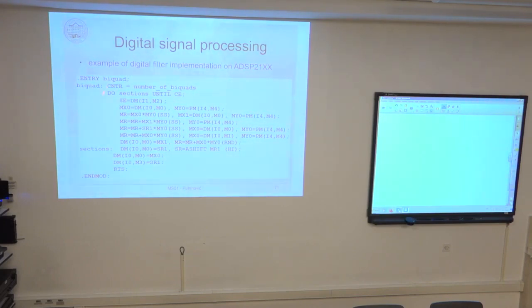And you have a dual loop, and this dual loop is also a hardware controlled loop. It has dedicated hardware support to implement a zero overhead loop. Normally, for a classical architecture, you have a general purpose register, you initialize this register, decrement or increment, compare with some value. If not, jump back to the top of the loop. So you lose many cycles just to control the loop counter, conditional jump, and so on. Here, you don't have a single such instruction.